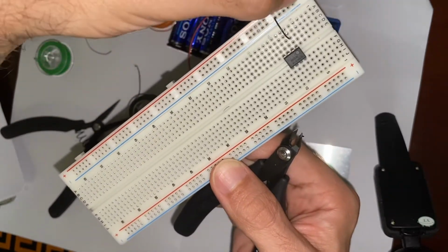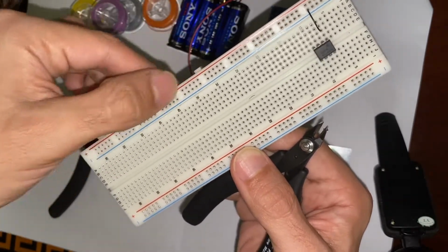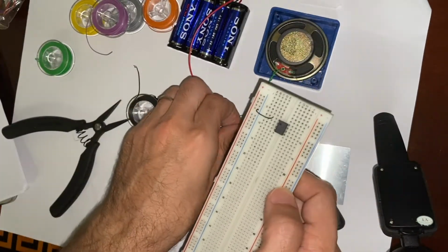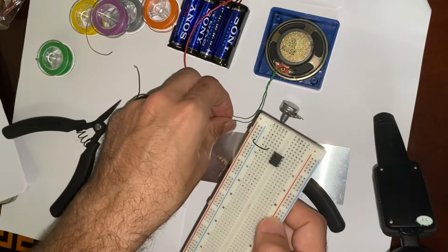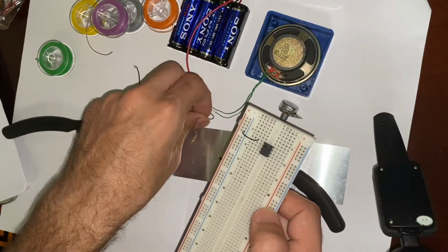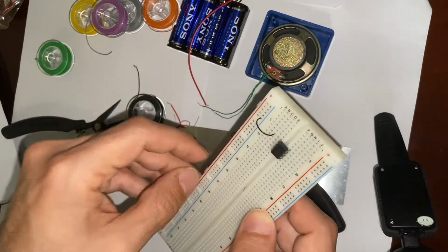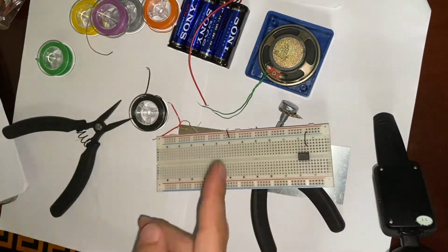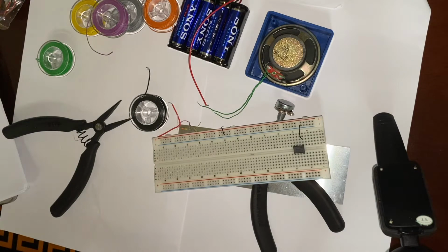So I'm not sure whether the first half of my breadboard and the second half are all connected, because different models of breadboards have different connections to the power rails. So I have one pin connected. I will connect here a little jumper cable, and I will use the multimeter to see if they're connected. I cannot see with my eyes.